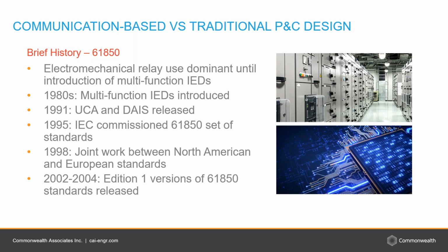However, in the 1960s, data acquisition systems became viable, which could collect measurement data from substations. But these systems were still limited by low bandwidth. Now, in the 1980s, multifunction solid-state relays were introduced. These relays could perform protection, control, and monitoring functions. These types of relays are known as intelligent electronic devices, or IEDs. A single IED is able to collect thousands of analog and digital data points.